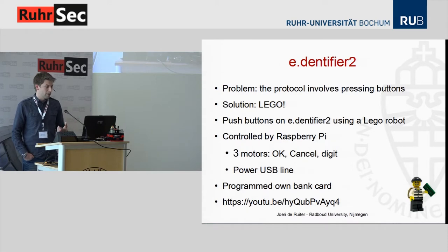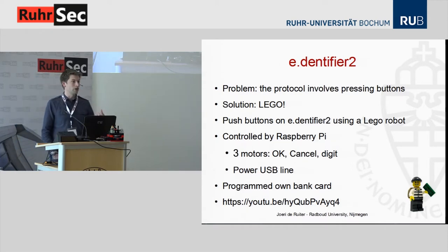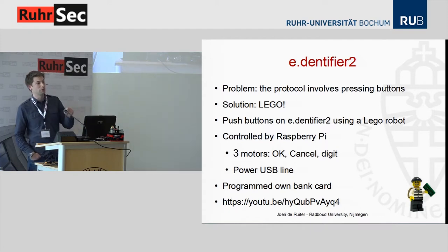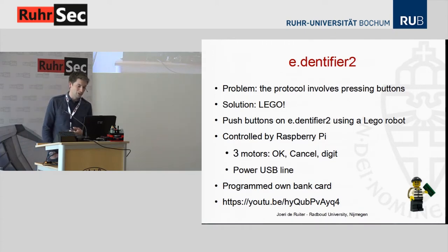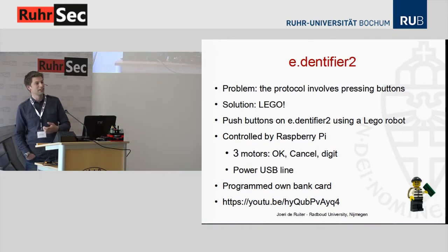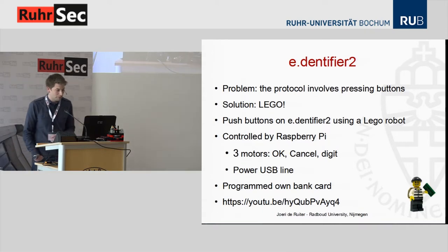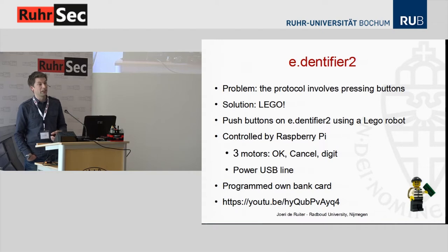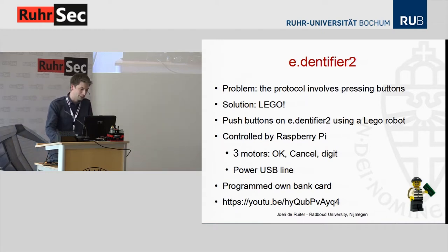During this project, we also found out that apparently the buttons on these devices are not meant to be pressed thousands and thousands of times. At some point, I got some non-deterministic behavior. And after lots of debugging, I found out that once in a while the button got stuck because it just wore down by pressing it so many times. But luckily we still had 9 digits left, so we moved the motor a bit and then we could continue with the same reader again.